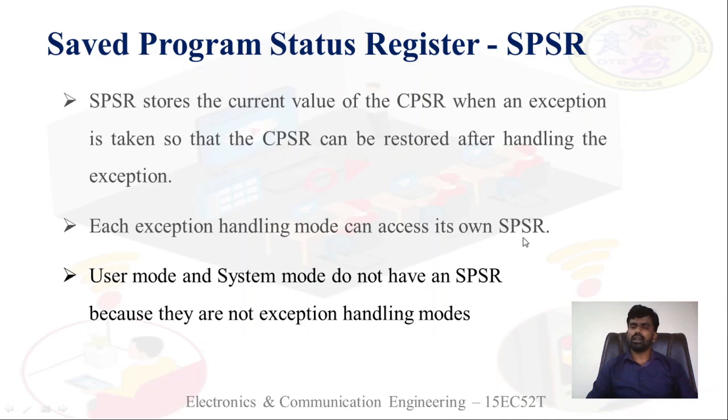The remaining 5 modes are exception handling modes, and they have their own SPSR. Which are those exception handling modes? Abort mode, supervisor mode, undefined mode, FIQ mode and IRQ mode.